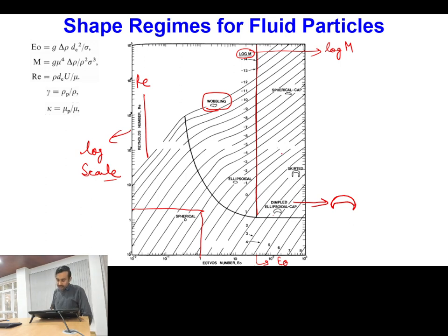Okay. Further increase of the Morton number leads to a shape something like this, where you have the continuous phase penetrating within it. So this we call a skirted shape. And a shape which has a pure spherical cut with a flat base or wavy base, that we call a spherical cap shape. Okay, is this point clear? Are all clear with this idea?